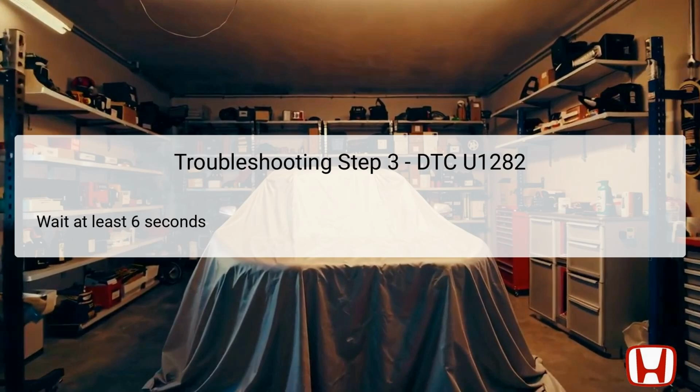Once the 6 seconds are complete, the technician can confidently check for any DTCs using the HDS, knowing that the systems have been properly initialized. This attention to detail is essential for high-quality diagnostics. The final troubleshooting step involves checking for DTCs using the Honda Diagnostic System, HDS, after the ignition has been turned on and at least 6 seconds have elapsed. This action is critical in diagnosing whether DTC U1282 is still present.